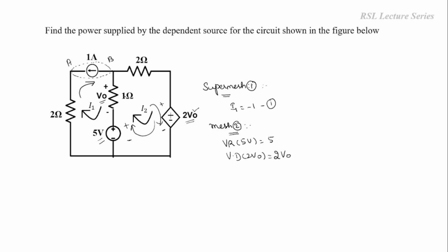So next we have to write down the voltage drop across 1 ohm resistor and 2 ohms resistor. So now the voltage drop across 1 ohm resistor is equal to current flowing through this particular 1 ohm resistor into 1. Okay, by Ohm's law V is equal to I into R. So here this 1 ohm resistor is lying in between mesh 1 and mesh 2. So the current flowing through this 1 ohm resistor can be written as either I1 minus I2 or I2 minus I1, because I1 is flowing in the downward direction from mesh 1 through this 1 ohm resistor.